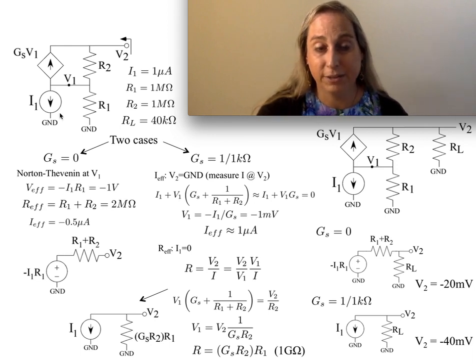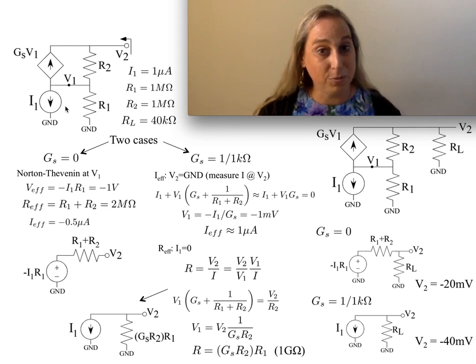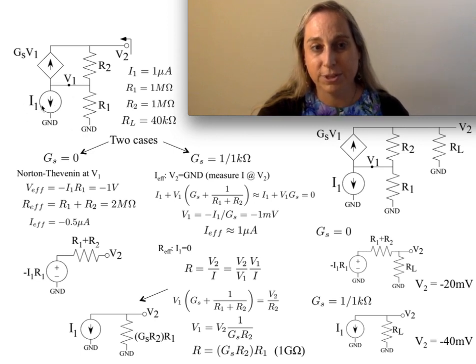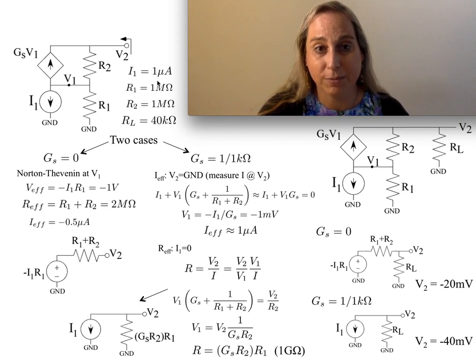Well, in that particular case, the easiest solution here, and again, every solution depends a little bit on where you're starting and what you're going to build from, is to do a Thevenin-Norton equivalent of this. I transform this, and what this gives me is actually minus 1 volt, times basically just this R, and these two will be in series. Why minus 1 volt? Well, because I have 1 microamp going downwards. That's where the minus sign comes from. And then R1, which is 1 megohm.